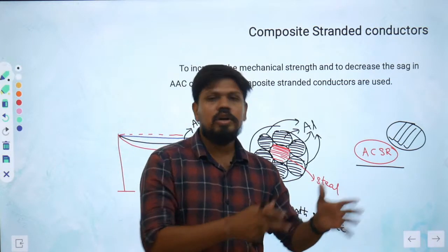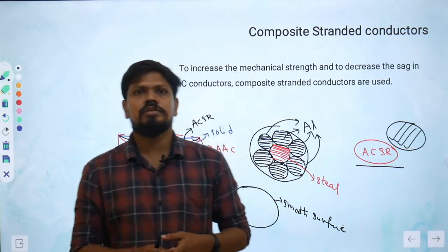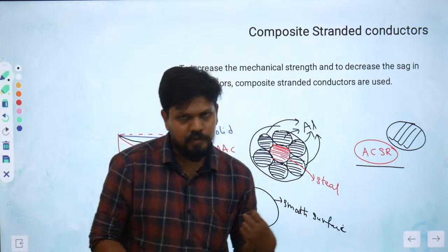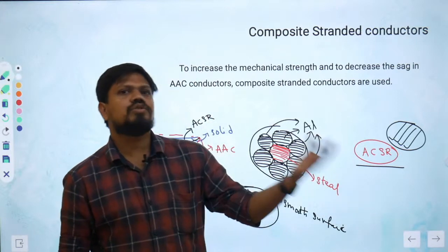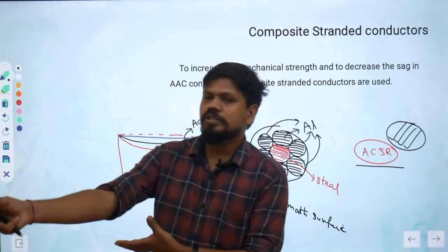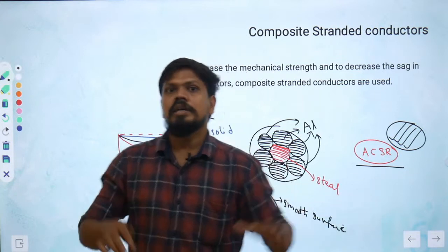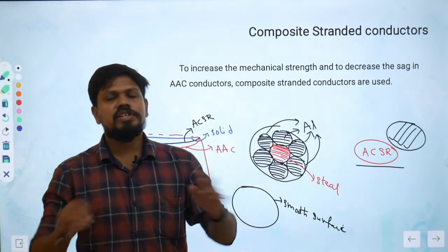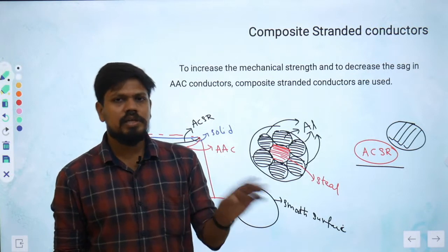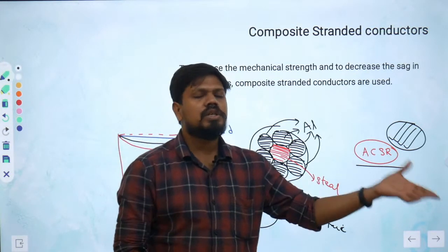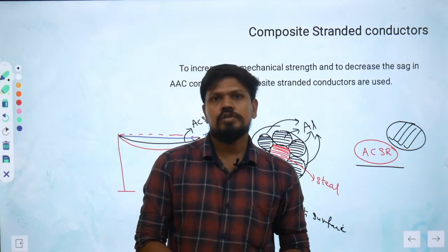Economic load dispatch means whenever there are more power stations that can supply power for us, what has to give how much power. Like this power station has to give 50 megawatt, this power station has to give 20 megawatt. Like that we have to make the power generation economical. You need to understand all these concepts later. After that, protection concepts also you need to know.